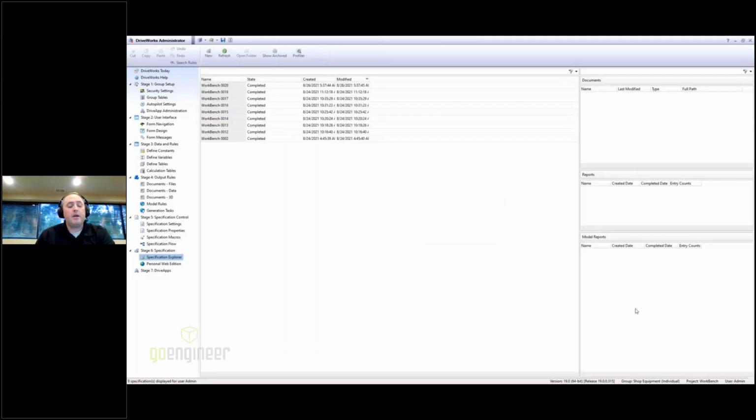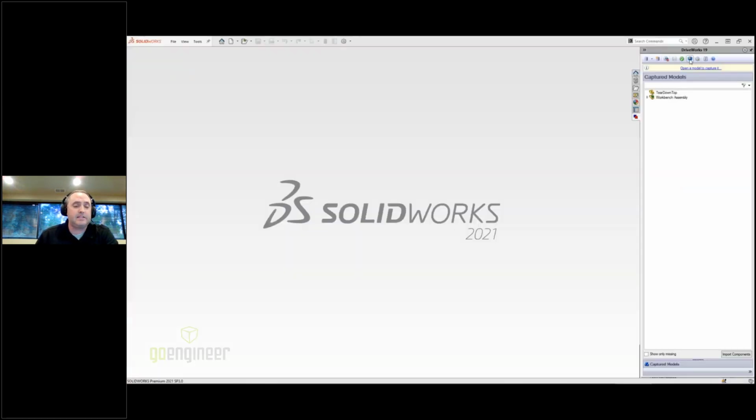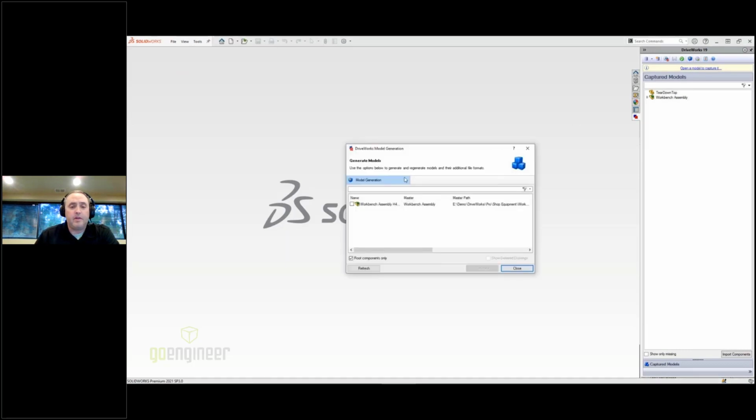All right, now we're going to manually generate our models again. But pay a little attention this time because you're going to see a drawing pop up. We haven't talked about drawings yet, just due to time constraints, but we can definitely generate drawings. And you're going to see in this process that a drawing gets opened and properly scaled. That is why I chose those maximum numbers. So flipping over to SolidWorks, we're going to grab this and generate our data set that we just selected.